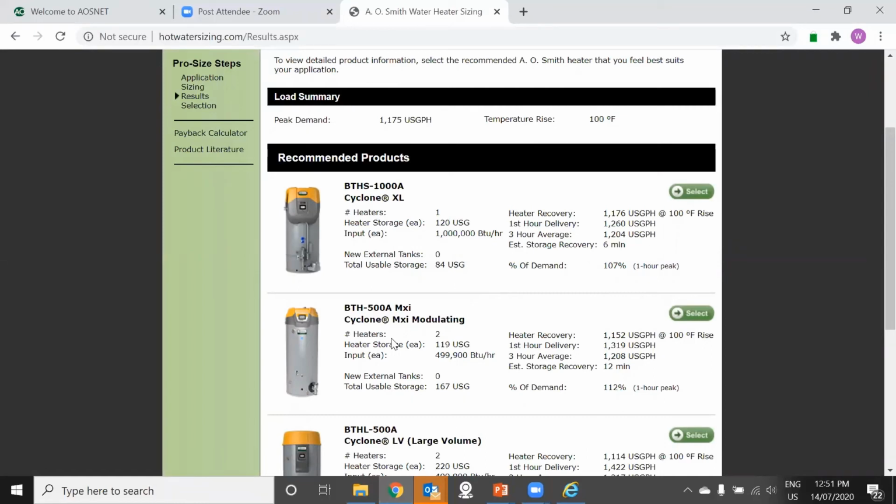It gives you liters of storage per occupant and also a recovery rate in liters per occupant. Then you multiply that by the number of occupants and find the graph, and it will show you all sorts of different storage and recovery details.